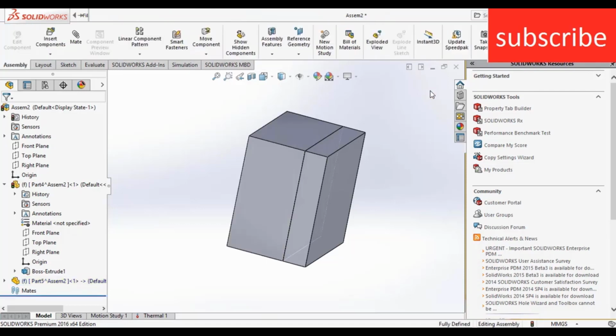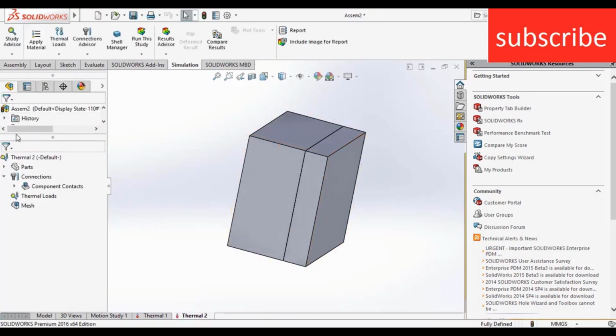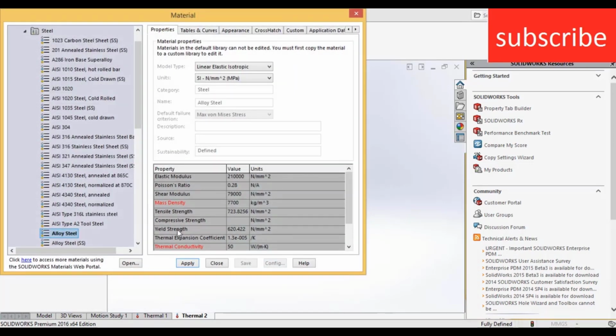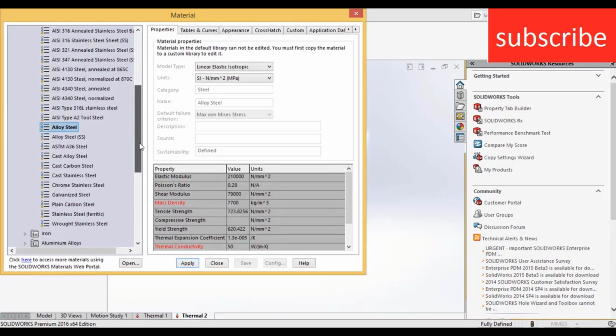Now exit this simulation, edit part, click on new study, click on thermal, click OK. Click on parts, select part 1, click apply edit material. The first material I am applying is alloy steel, as you saw in the first case. Now for the second part, click on apply material, select any material as per your requirement, for example cast alloy steel.